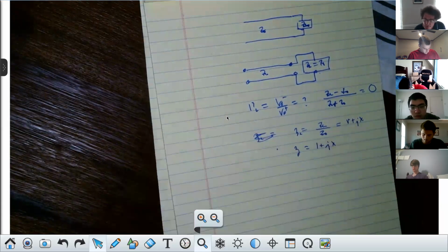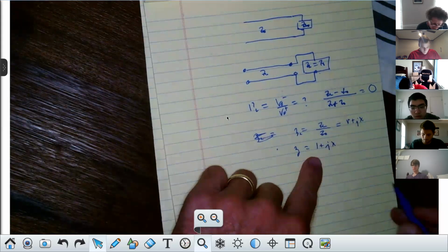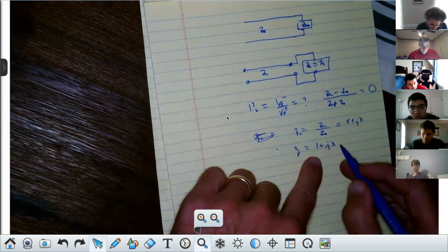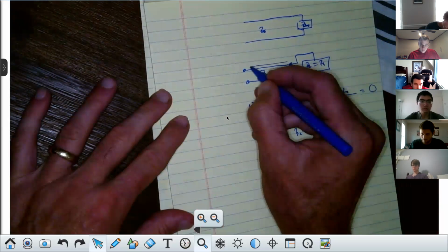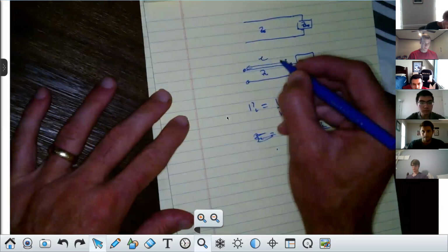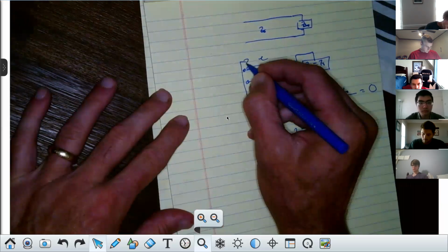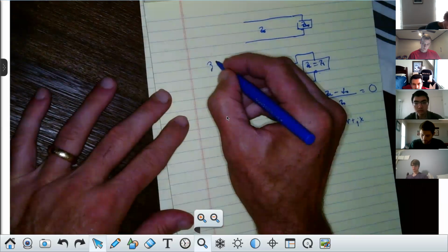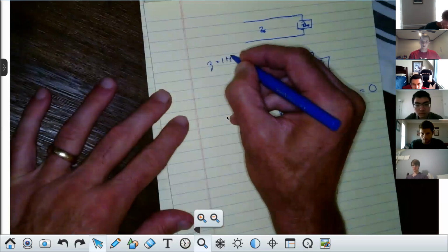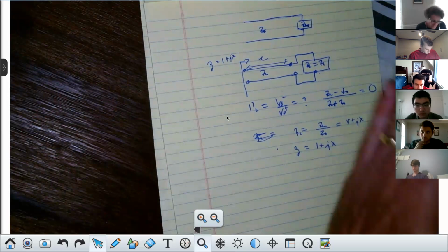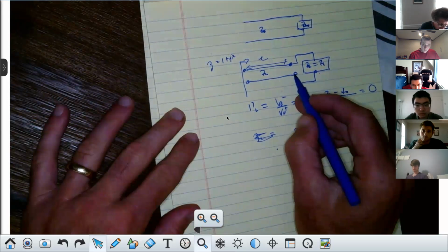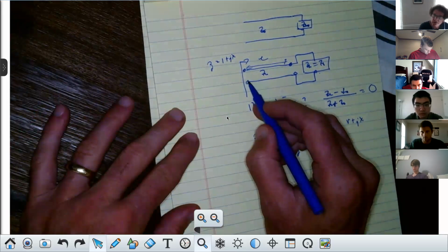Now, listen to me. What if I added a component at that point to get rid of this JX? So you're going to move a distance L until the normalized input impedance Z would be equal to 1 plus JX. That's your first step, and I'll take you through it. Follow me? Once I come into the Smith chart, I keep moving until I hit 1 plus JX.